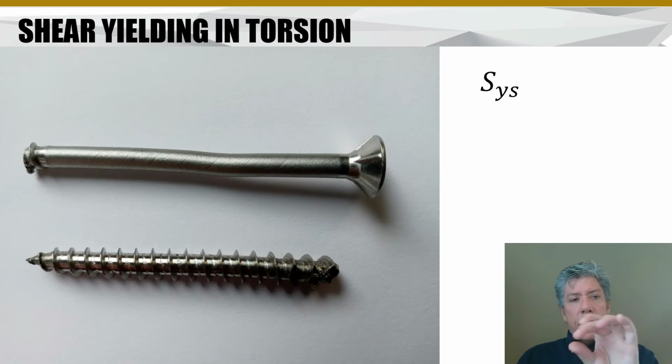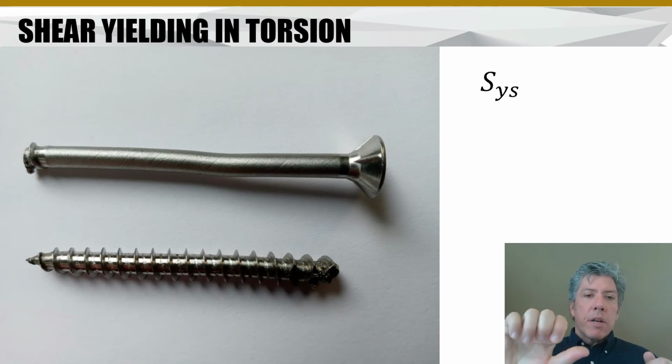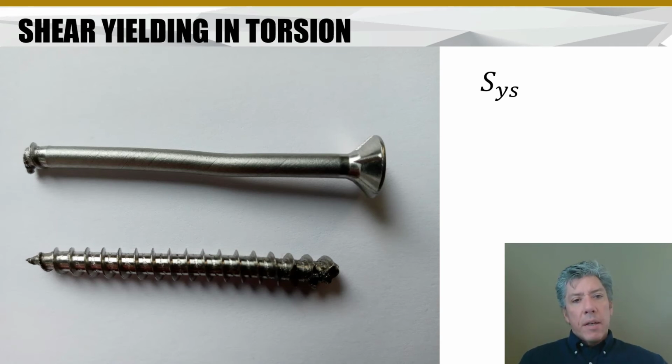You'll notice that we're looking at the body section. It broke in the threads. That makes sense. That's where there's the highest stress concentration, the smallest diameter of material available. But you can see that I was actually screwing it forward, right? Because it was going in right-handed, and you can tell that it yielded in that sense. Look at the shoulder, basically that solid section that's sort of bent. You can see some almost 45-degree lines in the image there. Those lines used to be essentially straight along the length of the shaft. So this thing really yielded along the entire length.